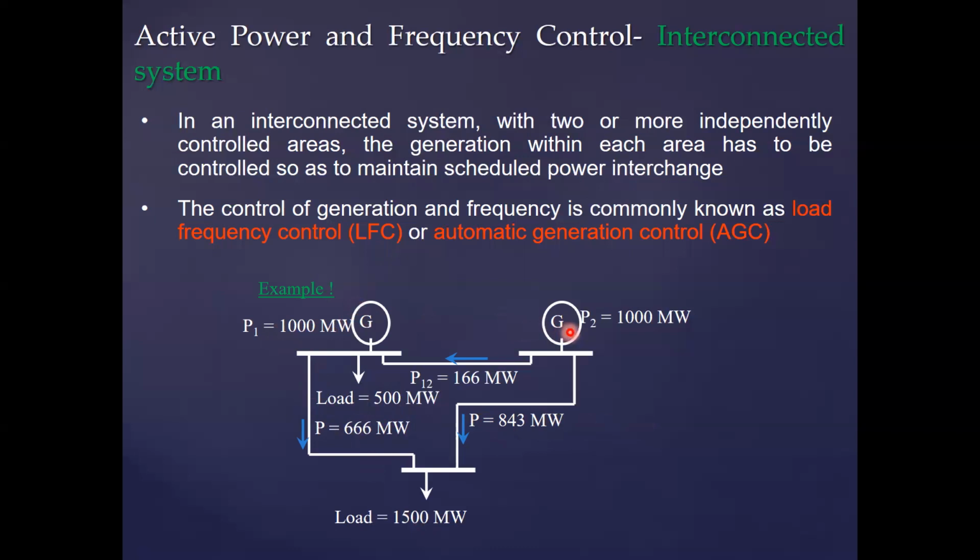Offline, we have the model developed for the system, and for different contingency levels you apply some load change here and here, and for every contingency level we determine what should be the change in the power from this set of generators and from that set. Then we develop power flow equations and have different algorithms, such as the Gauss-Seidel method or the Newton-Raphson method.